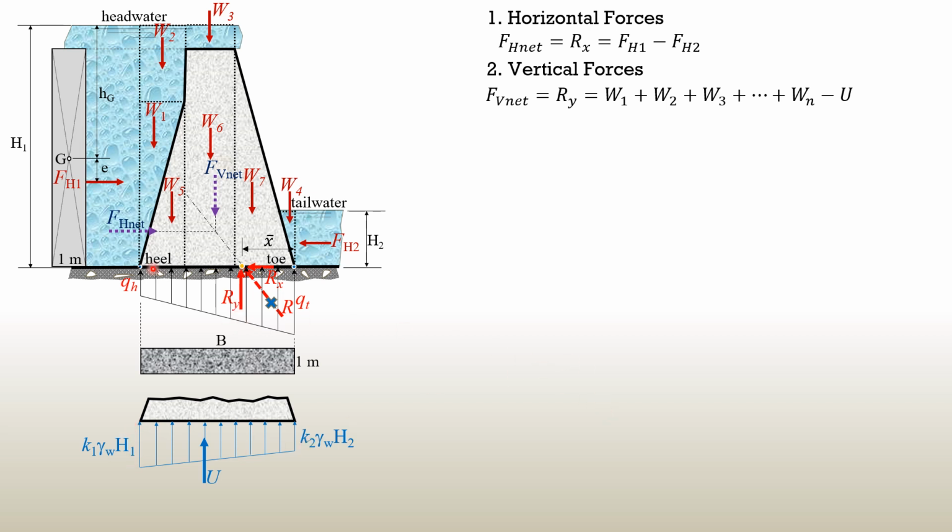Likewise, Ry is also the volume of this soil pressure diagram, which is important in computing the intensities QH and QT later instead of memorizing formulas for combined stresses in the mechanics of materials. So next, we have to ensure safety of the dam, we have to compute or evaluate these safety factors. These safety factors include factor of safety against sliding, which is Fs sub s,